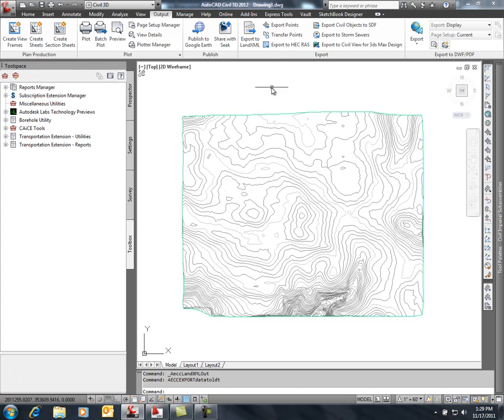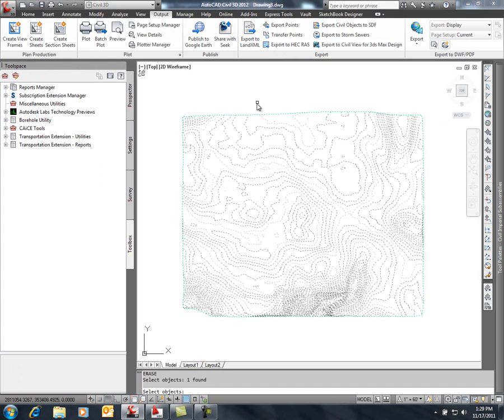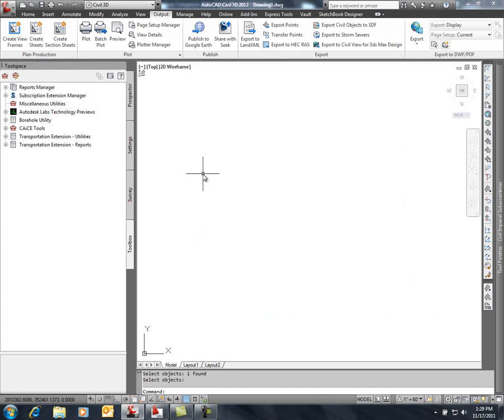We're going to come back to the Civil 3D side, and you know what? I don't need the surface anymore because I've already migrated it back into Land. At this point, the next data that I'd like to bring in, I was given a shapefile that contains my structures and my pipes. I'd like to immediately convert that into geometry that I could turn into a pipe run or deal with on the Land Desktop side. So let's do something similar here.